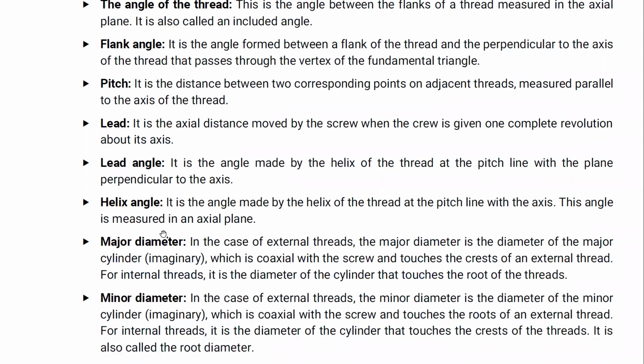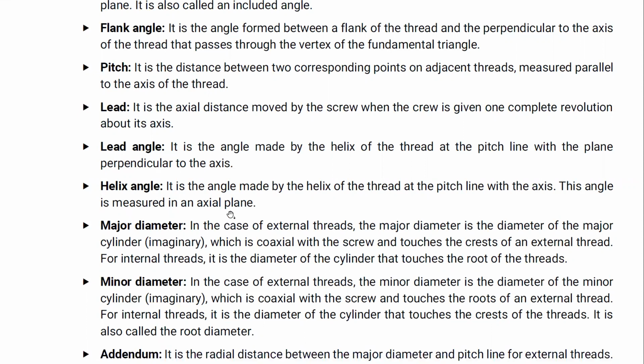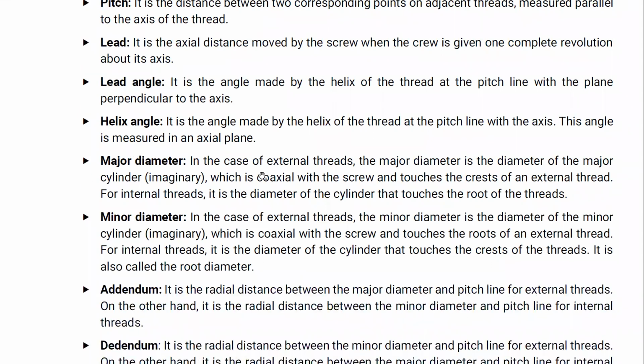Then again, the helix angle is made by the helix of the thread at the pitch line with the axis. Here, the angle measured with the plane perpendicular to the axis is the lead angle, and the angle along the axis will be the helix angle. It is measured in the axial plane.